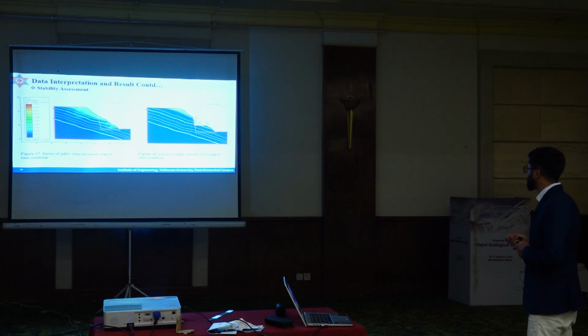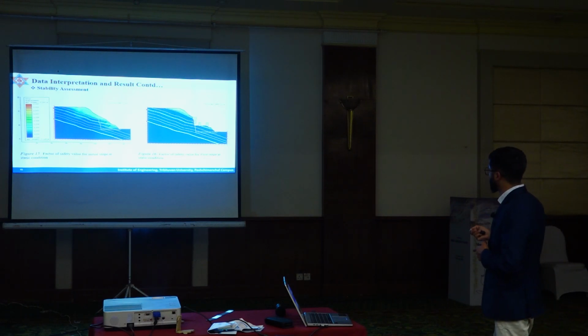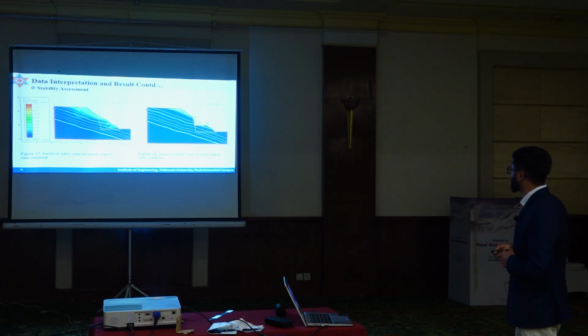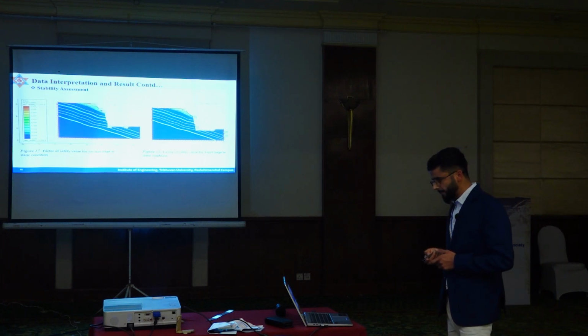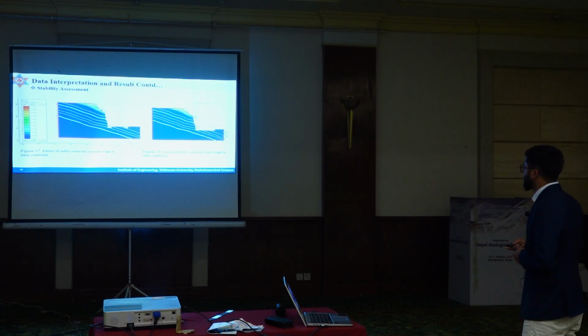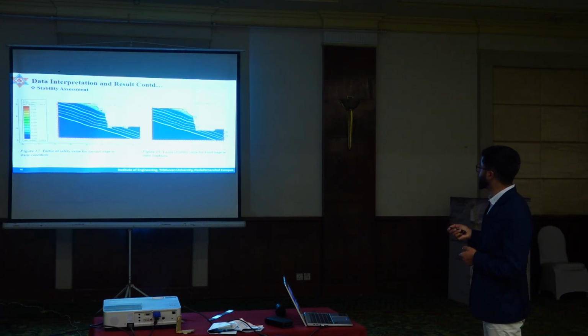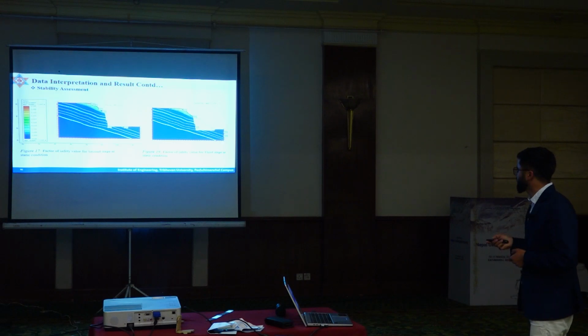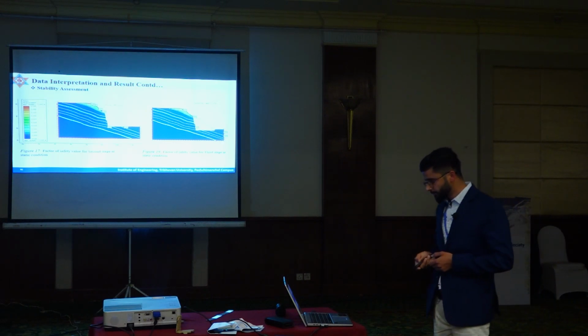And here, at the first stage of excavation, the factor of safety reduces below 1. That is, the stress reduction factor is less than 1. It is 0.8. So the portal is unsafe after the excavation and before application of support. Here, at the second stage of excavation, the factor of safety reduces to 0.76, and here at the third stage of excavation the factor of safety further reduces to 0.75. That we can clearly see from here.